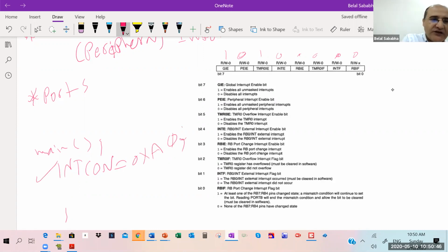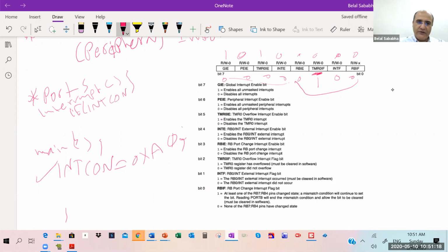Now the interrupt is enabled, timer 0. When I write the interrupt service routine, to check if what's bringing me here is the timer 0 interrupt, I check for its flag, صح؟ I check for this flag if it's 1. So I mask everything else. I AND everything here with 0 except for this with 1. So I AND INTCON with 0x04. Then what brought me here is the timer 0 overflow, صح؟ This is for timer 0 interrupt.